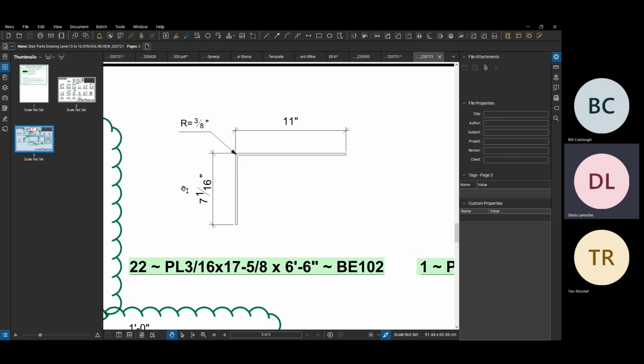We don't expect people to show up there with calipers to figure out if something is installed to within the width of a hair. There are parts we've done in the past, machined out parts, special fittings, where you did need that high tolerance, and you also include a plus or minus 0.005 inches of tolerance here and there. That's kind of rare and not really something we do much of anymore.